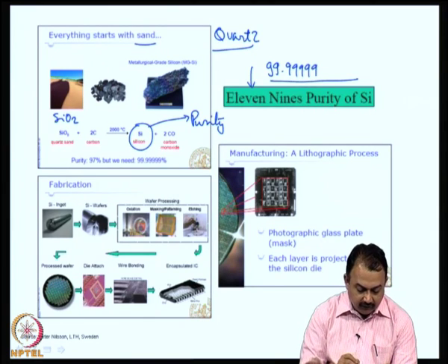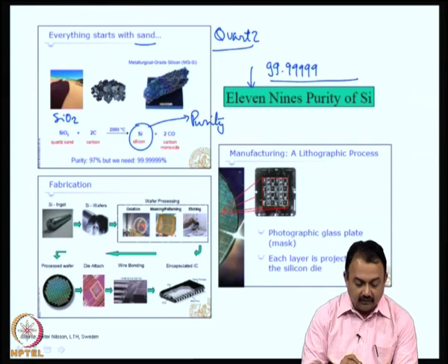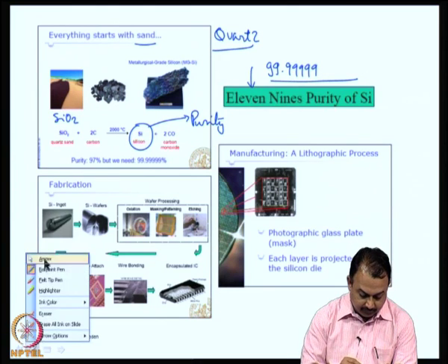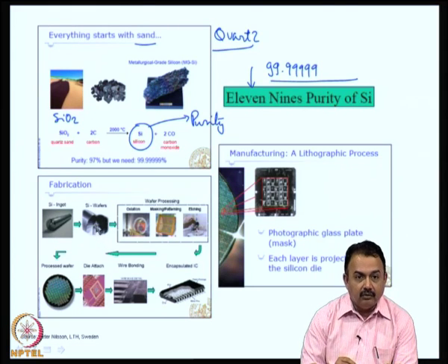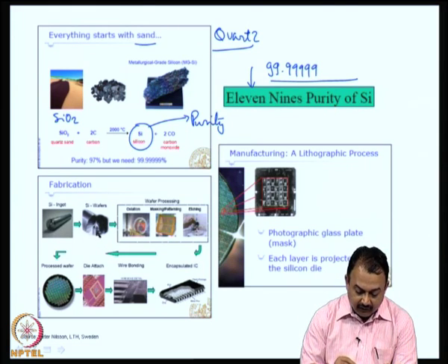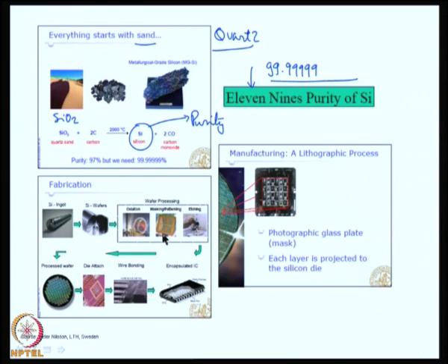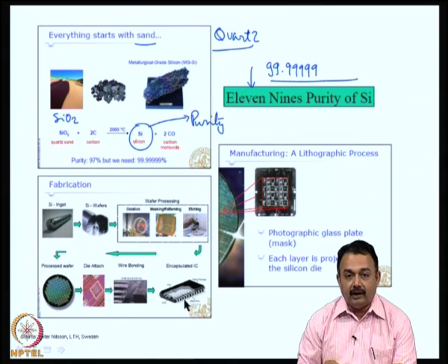Now, very briefly, if you look at this particular slide, we start with silicon as an ingot material. From there the wafers are generated. This is an ingot material, a rod of pure silicon, and here you have the silicon wafer. Then the wafer processing takes place, including oxidation, imaging, patterning, etching, and then the processed wafer is ready for die attach, which I explained. Then comes the wire bonding and then encapsulating the IC in a plastic package to define the final package format.